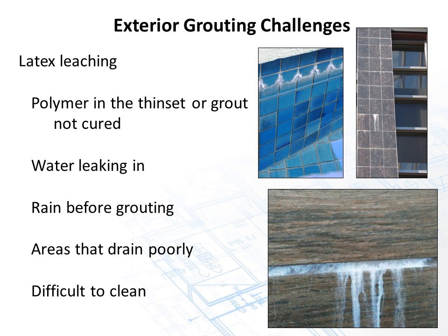What you see in this upper left-hand corner is a water feature in Maui. I had to travel far to get this picture, but they obviously filled this water feature too quick. So the latex in the mortar and/or grout dried at the very top surface of where the water level is. So water is terminated right here, and the latex dries right along the top of it, obviously allowing for the water to move. I do not know why this latex is leaching down the face of the stone, but I'm going to assume that there's a leak somewhere up above here.